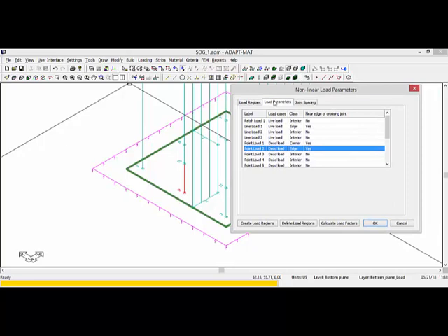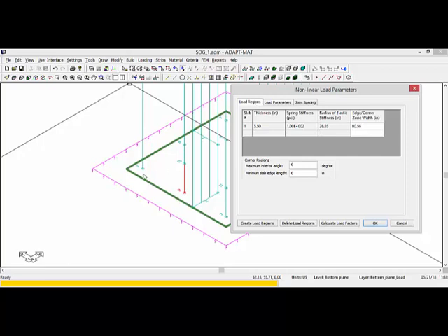So once we're done with that, we need to determine what the load regions are. These load regions are used to classify the loads in their position and proximity to the edge of the slab, whether it's a corner zone, an edge zone, or an interior zone. And you can see this itemizes the slab regions. We have a slab region of 5.5 inches thick. Spring stiffness, the radius of elastic stiffness is shown here, and the edge is 3 times this value here, which is 80.56.